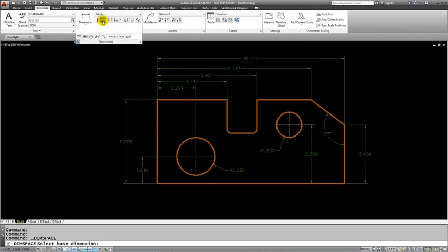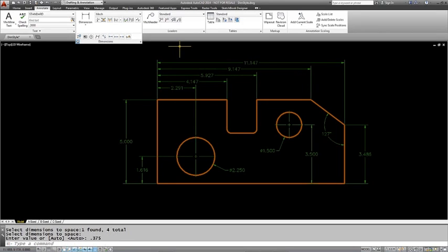So I'm going to go ahead and select the object. I just don't like my spacing. And the second object and the third object and the fourth and the fifth and sixth. And you can see that the spacing's way off. So I'm going to select a value of 0.375. So it's a little bit wider than I need. So I reset that spacing. You know, I better reset the dimension spacing over here also to get the spacing here the same. So it looks very nice.